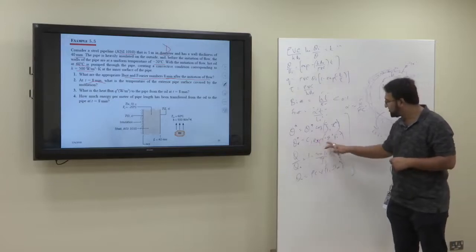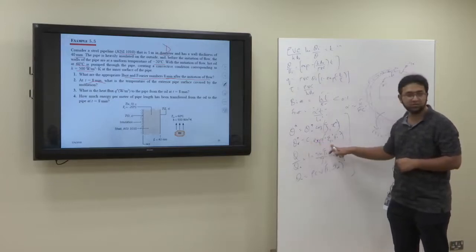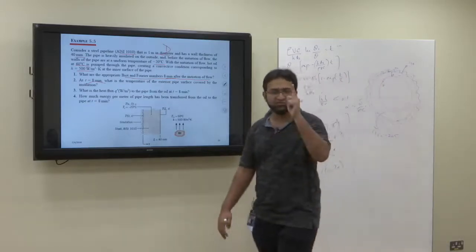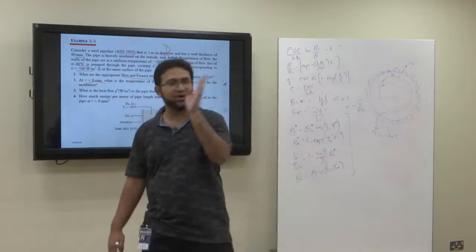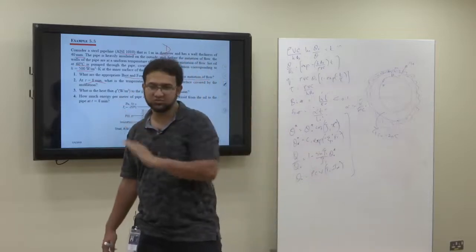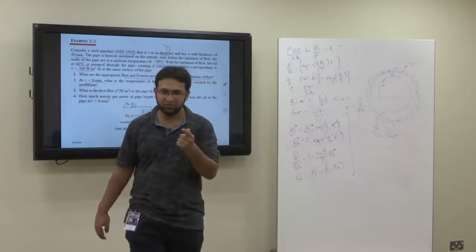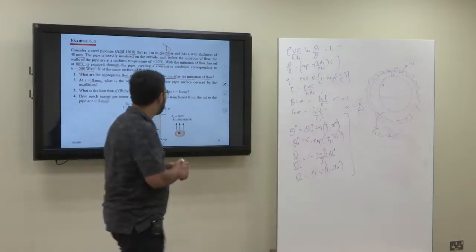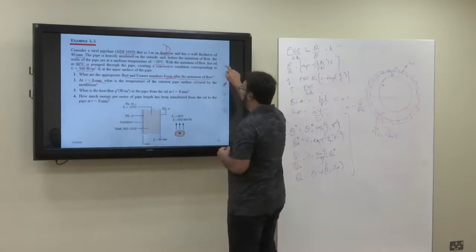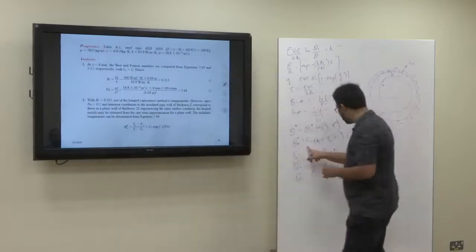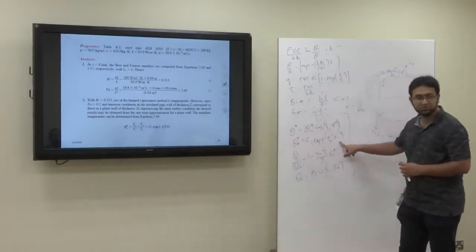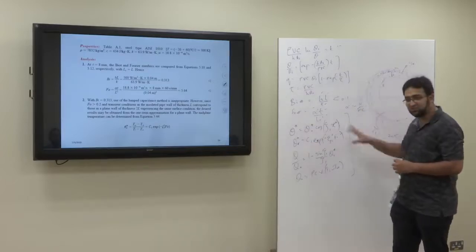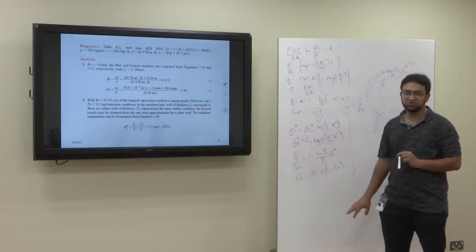Now we need just these two constants, C1 and eta 1, right? We can get these constants from the table, because in the table you have the Biot number, and based upon the Biot number you have these two constants. Okay, but for the plane wall. So we'll get this from the table, and so now we have C1, eta 1, F naught, the Fourier number. We know all these things. Substitute the values, you will get theta naught star.